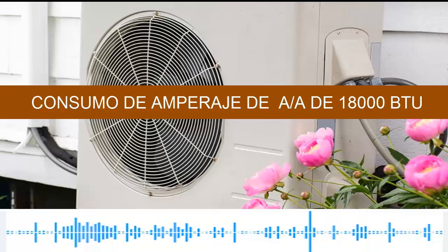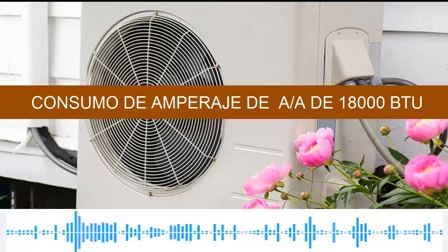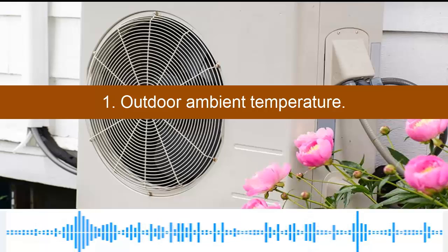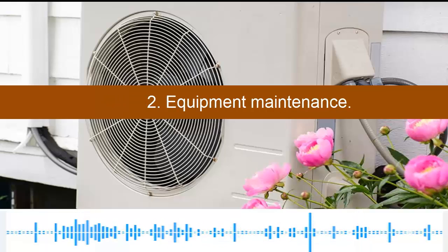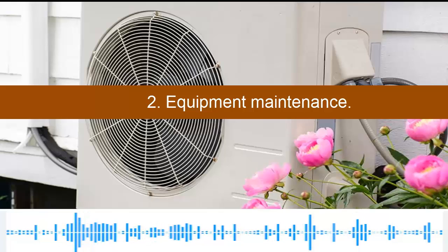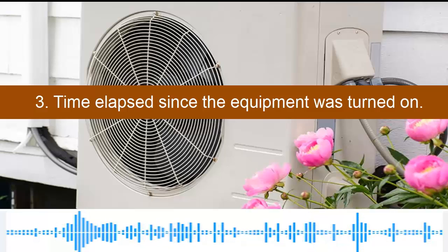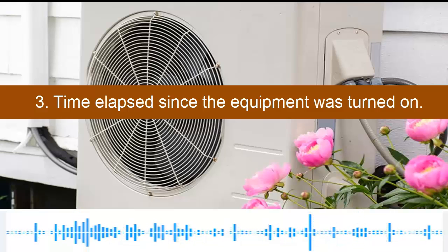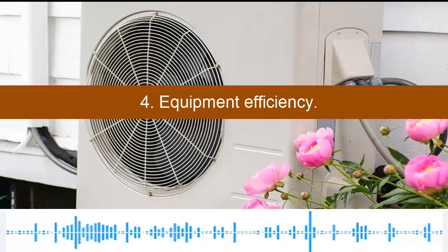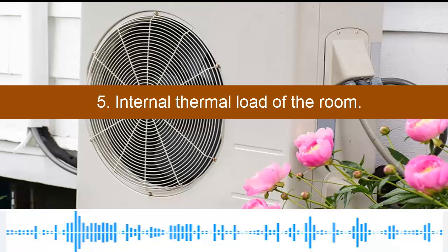To begin with, it's important to note that the electrical power consumption depends on factors such as: 1. Outdoor ambient temperature. 2. Equipment maintenance. 3. Time elapsed since the equipment was turned on. 4. Equipment efficiency. 5. Internal thermal load of the room.